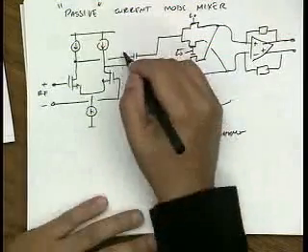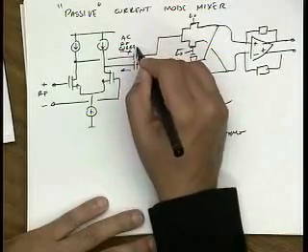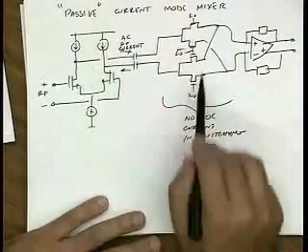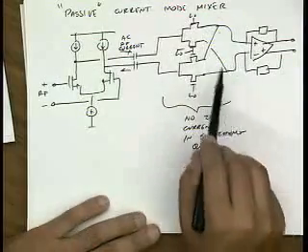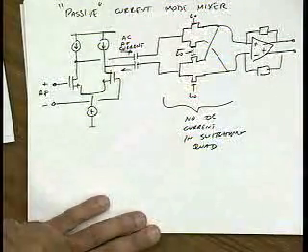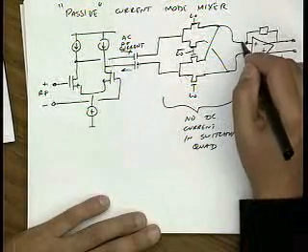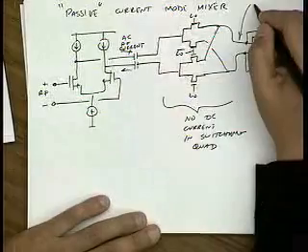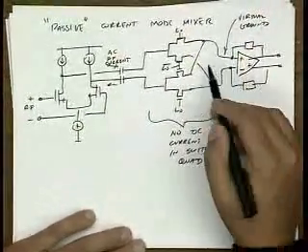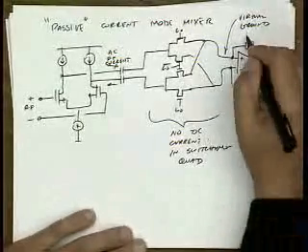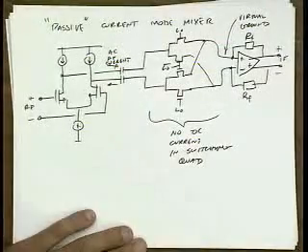Now the AC current will flow into the switching quad and basically will get commutated either positively or negatively, just like we saw in a regular Gilbert quad. And then that current will flow into this virtual ground. So this is a virtual ground. And then through this feedback impedance, RF, to produce an output voltage at IF. Okay?